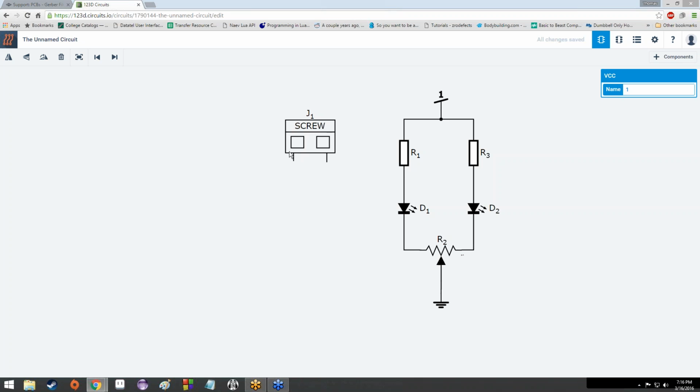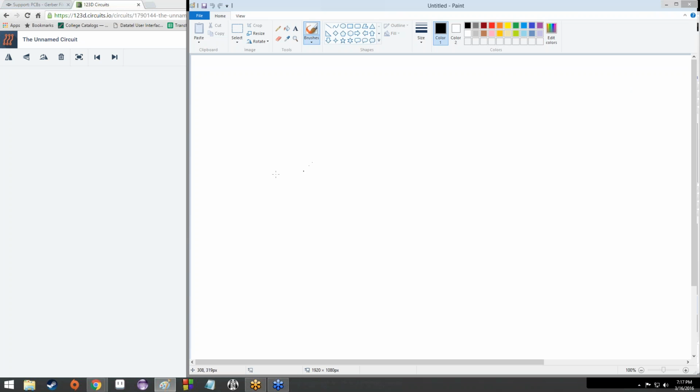For this particular instance, if we were to create copies of both this power and the ground, and name them the same thing, the result is that there is a connection created. It's assumed that they are the same thing.